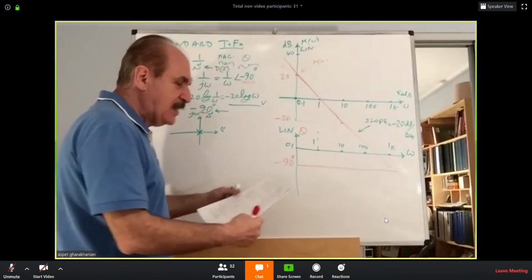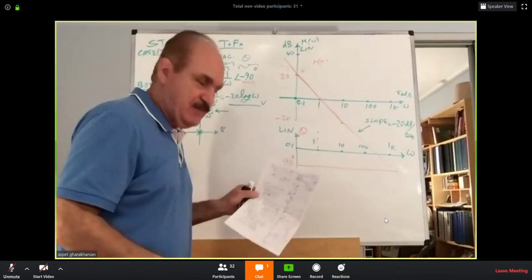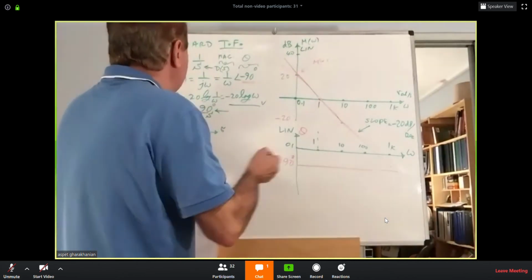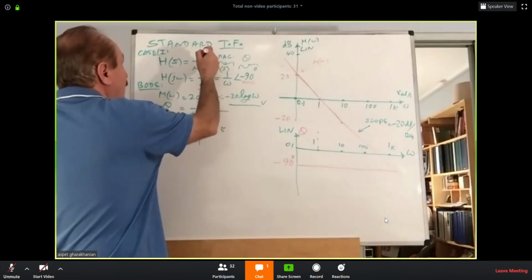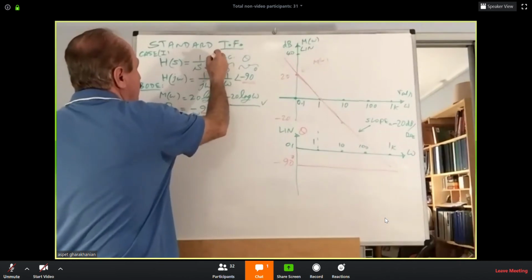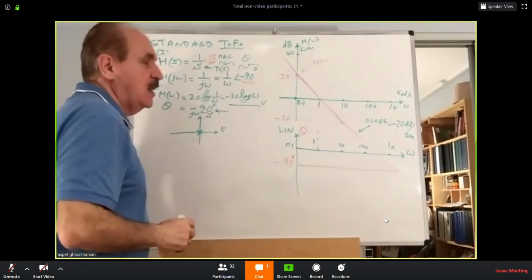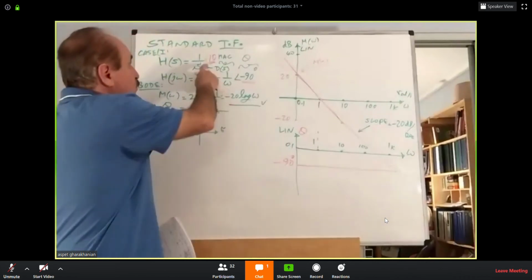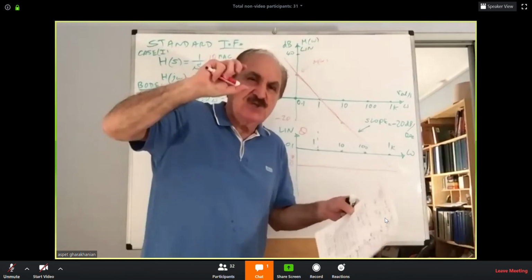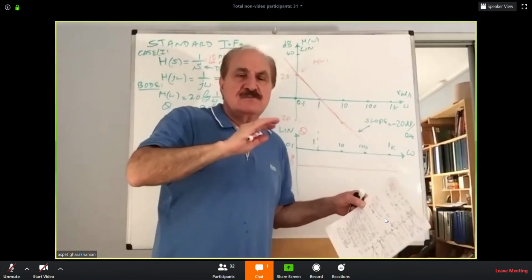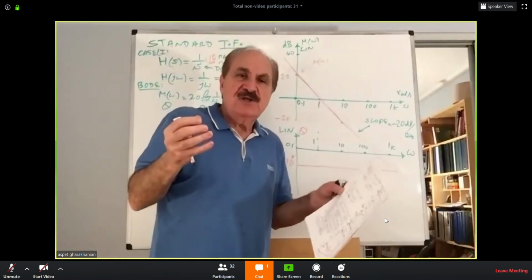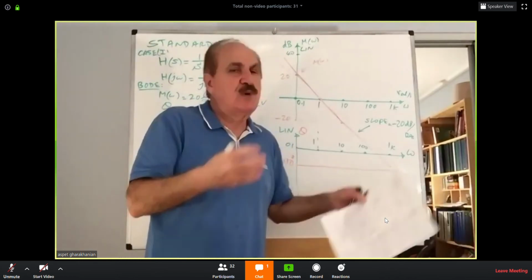Now, I didn't do it here in the paper, but what if there was an additional gain of, let's say, 10? What would you do? Generally, what is the Bode plot of numbers, constants? Not poles, not zeros, just constant. It is simply 20 log of that constant.